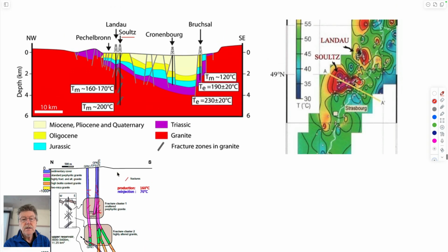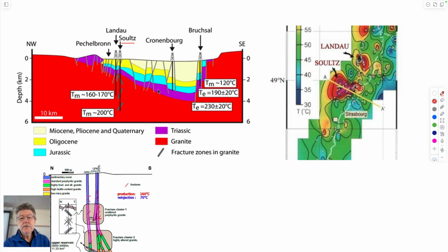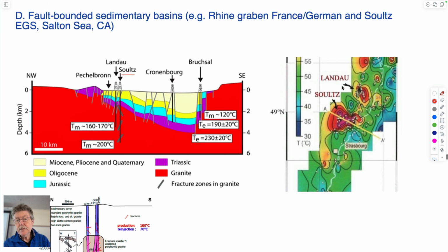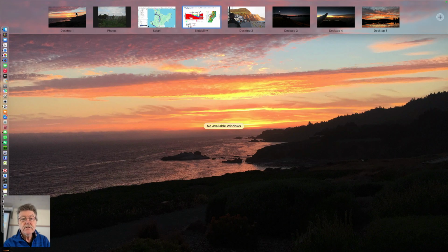And it exists on one of these interior boundaries to a continent. And if you look at a heat flow map or a temperature map at particular depths, you find this anomaly in terms of flow. So if you can measure the temperature on the surface in some way, by satellite imagery, or by measuring the temperatures in wells, you can make such heat flow maps to allow you to zone in on certain areas.